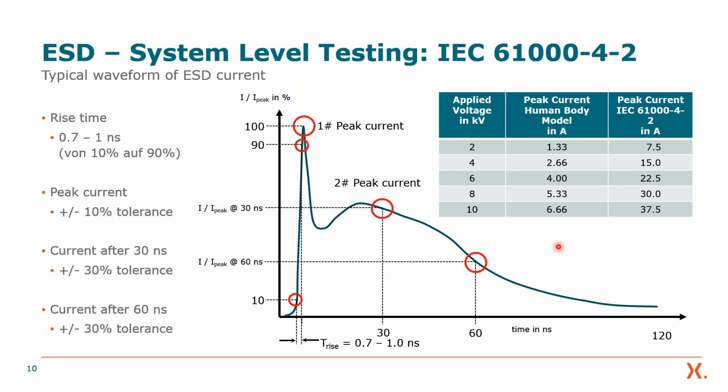However, when you look at ESD protection devices, this IEC test pulse is very often used as a device characterization test pulse. So it's also incrementally increased until destruction. And the reason is that ESD protection devices are robust enough to be handled in production. So you really don't have to care about human body and charged device model for those, but you want to understand how it behaves in a real-life application.